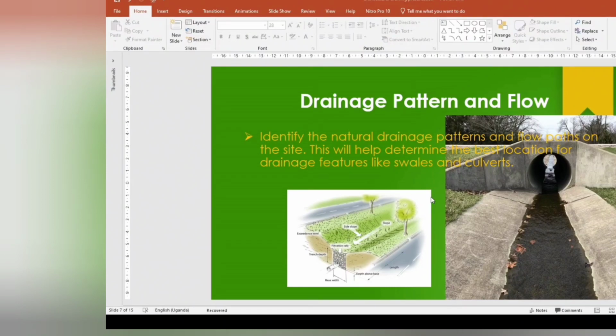So another thing you have to take note of when you make a site visit is to identify those areas, the utility lines such as water, gas, and sewage pipes, such that when time comes for you to draw the plan, you will know how your water will be disposed of from the site, being connected straight away to the public sewer line.